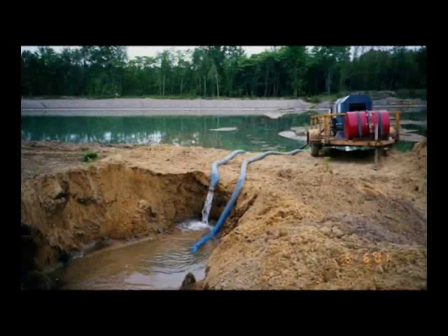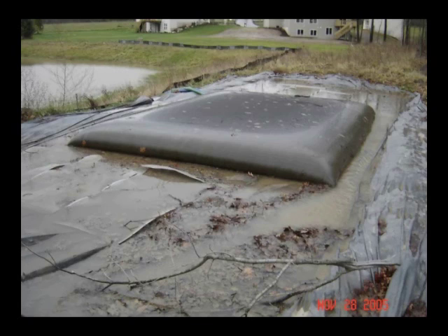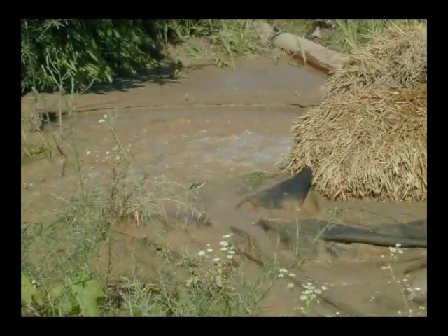The inspector must examine the suction inlet to ensure it is functioning properly and not clogged. It is important for the inspector to be sure the discharge is not causing erosion or carrying sediments to surface waters of the state or adjacent properties. When dewatering to a filter bag, sediment basin, or other structural containment system, the inspector must ensure that the discharge hose remains in place and that no sediments are leaving the containment system.